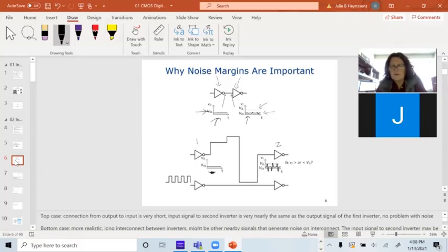As long as those outputs are below V in low, I'm okay. Maybe right here, I might have a false trip at a 1. But the way to improve this is, you know, I don't really have the luxury of controlling the routing. The routing's done by an auto router. It's going to do the best job it can, but it's going to do things like this.